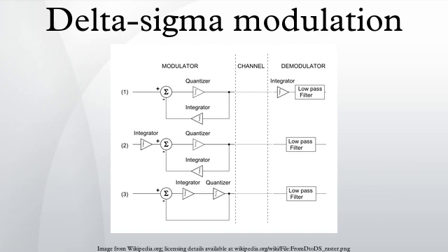The highly mathematical treatment of transmission errors was introduced by them and is appropriate when applied to the pulse stream, but these errors are lost in the accumulation process to be replaced with the errors associated with the mean of means when discussing the ADC. For those uncomfortable with this assertion, consider this. It is well known that by Fourier analysis techniques the incoming waveform can be represented over the summing interval by the sum of a constant plus a fundamental and harmonics, each of which has an exact integer number of cycles over the sampling period. It is also well known that the integral of a sine wave or cosine wave over one or more full cycles is zero.